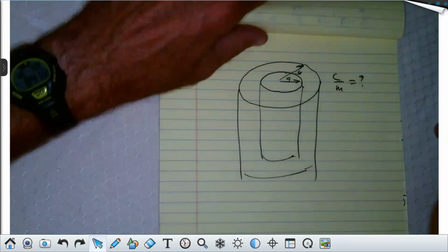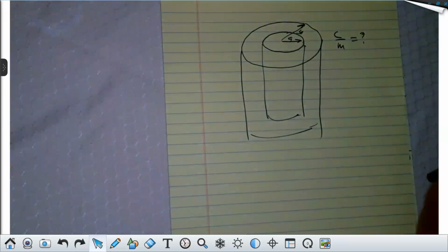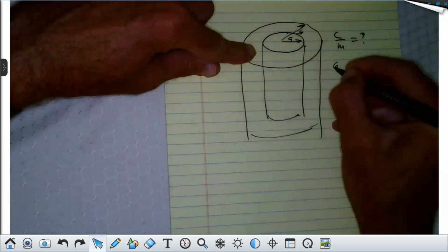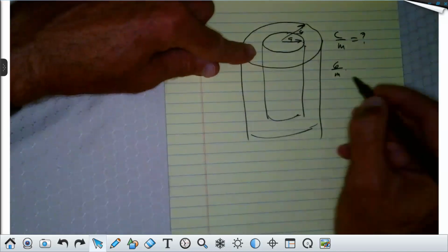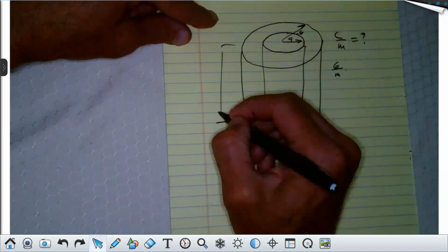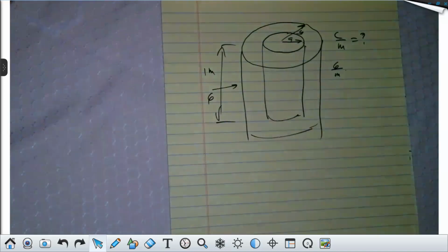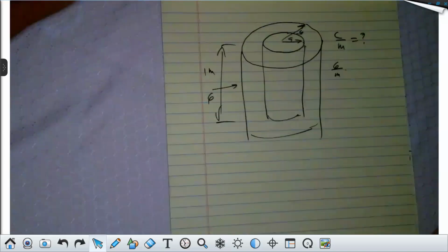So how do you do that? What are you going to do? Ron, well, go ahead. Assume a charge Q. All right, and it's per meter. Remember this. We're going to assume a Q per meter. We're just assuming this. So if we take a meter long section, we assume over that meter long section, it has a charge Q. Are you with me? It effectively, this is like rho_L, isn't it? The charge per unit meter is like rho_L.